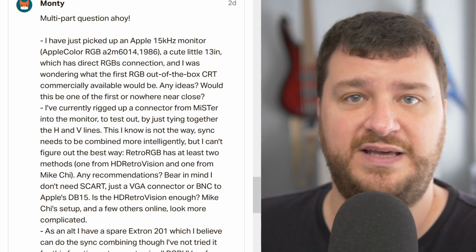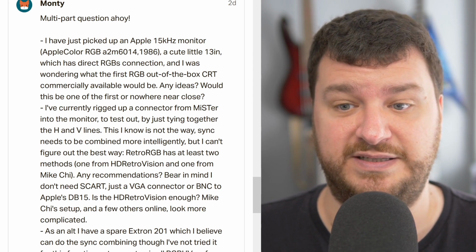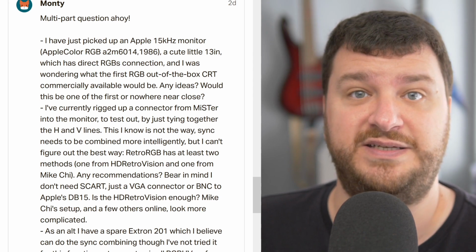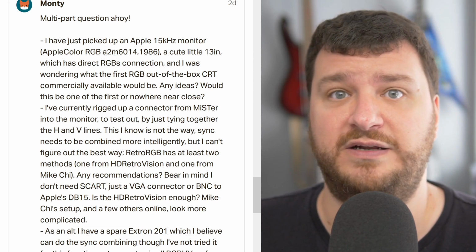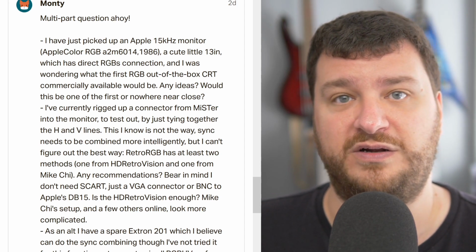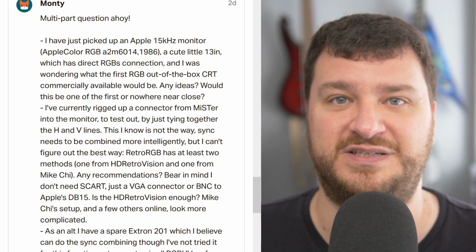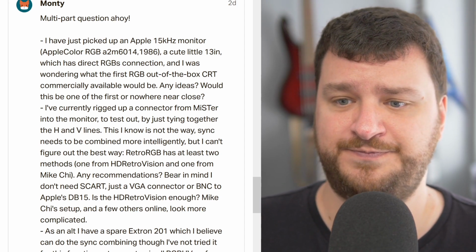All you have to do is set the INI file and then use any, in your case at least, VGA to BNC cable. Very often the 5 BNC cables, RGB HV, are the only ones available. That's totally fine. Just leave the other one unconnected, or maybe use some non-conductive tape and tape it back onto the cable so it doesn't flop around and hit anything. But that's perfectly safe and good to use.